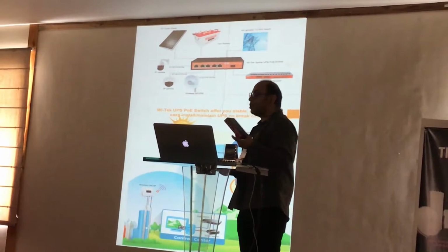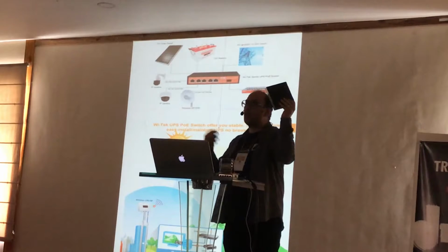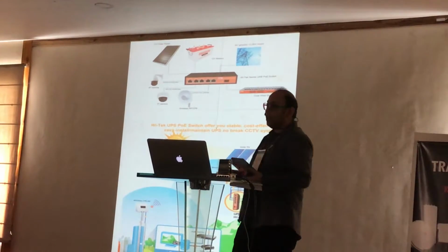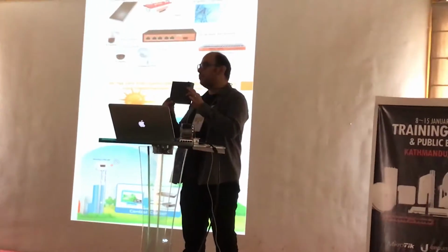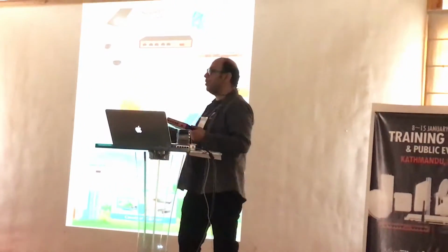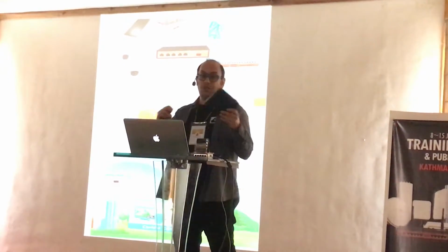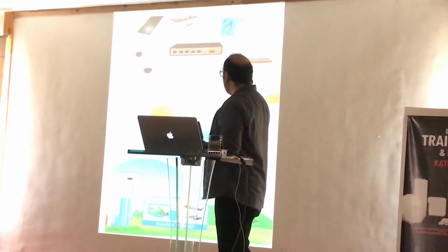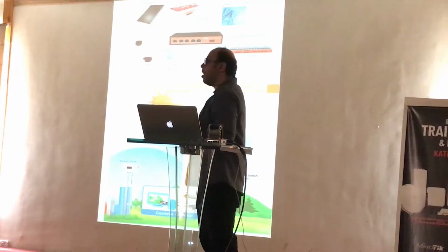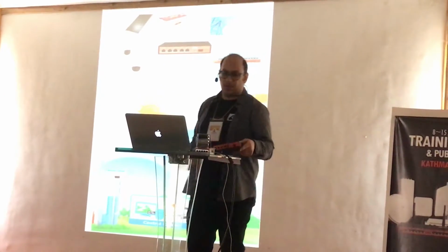Depending on your calculation, you may have 7 days of power with the battery, because you may need more than one battery. By having a good calculation, you can have 1 week without any sun, without any incoming power. You can save up to 1 week. It depends on your calculation, on your consumption, and on which device you use. If you use a very HD, very high quality camera, then the power consumption is more.